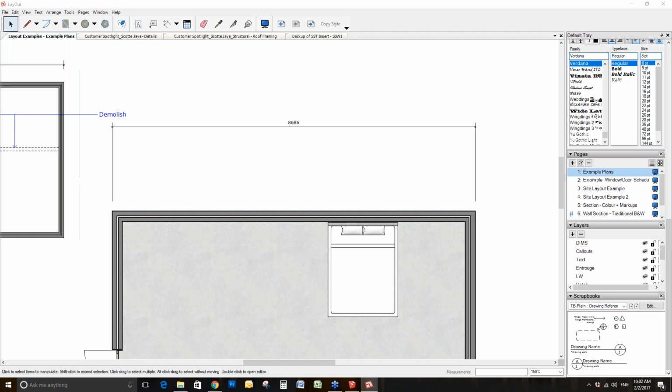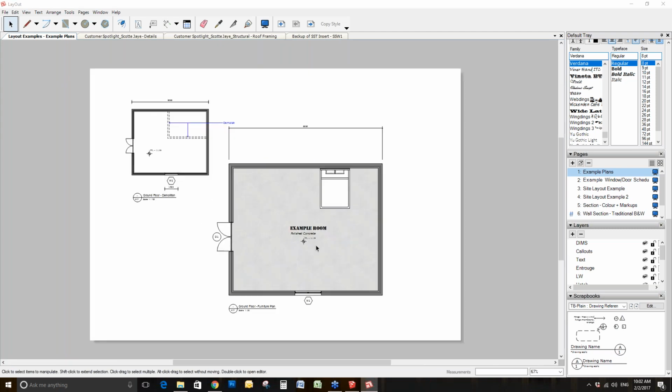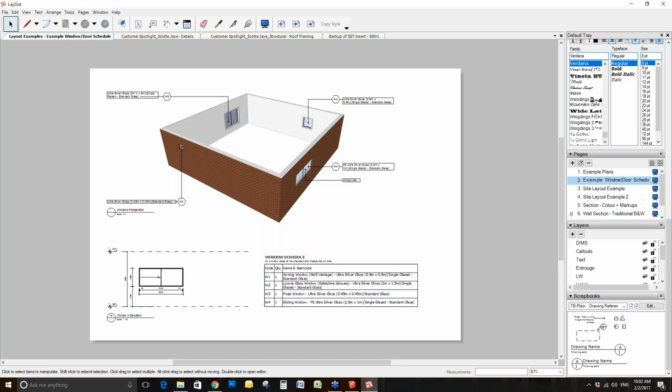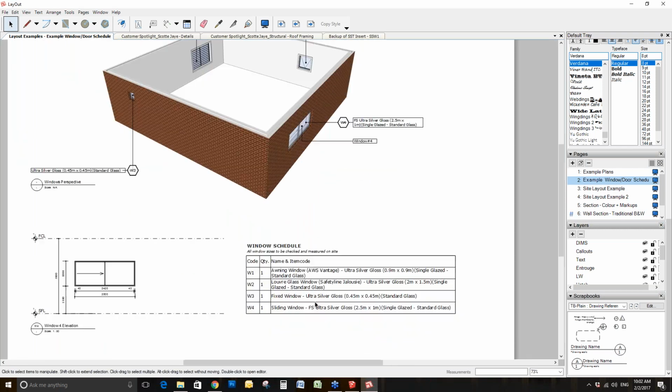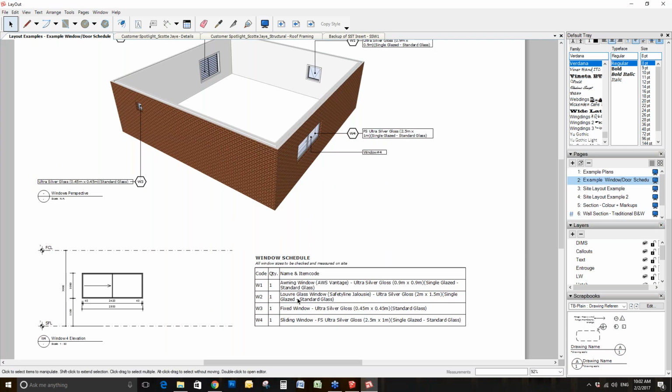I have another question about how you connect the window and door numbers from the 3D model to the window schedule. At the moment, yes, you need to, in the CSV file that I created, if I go into that, when I exported my takeoff with my window schedule, I simply went into my Excel document and added the different ones, but it's done in order. So it knows what is number 1, number 2, number 3, so you simply know that that's the top and that's the bottom. Unless you reorder them, and then obviously once you've updated your CSV, if anything changes, then it's a live link. So it's not really that much extra work.